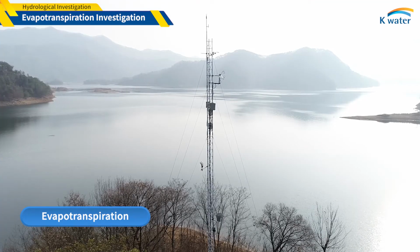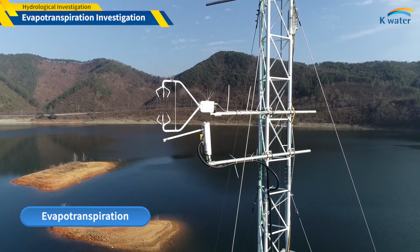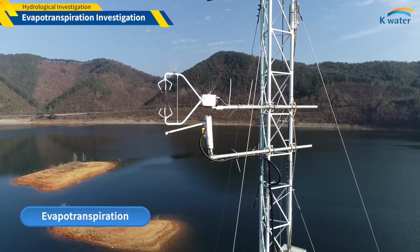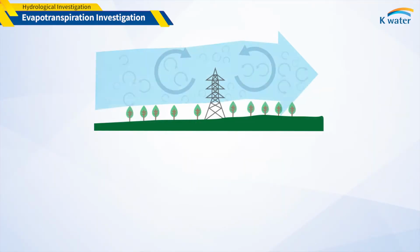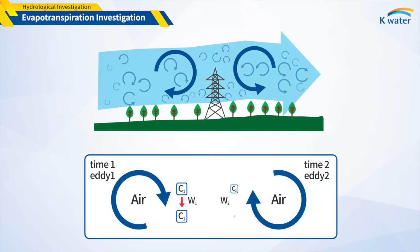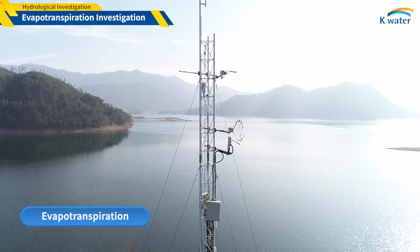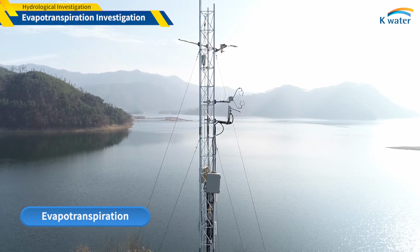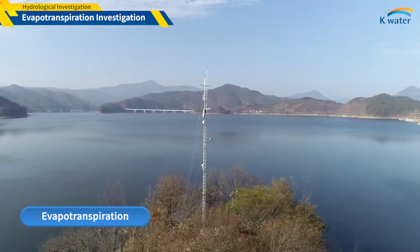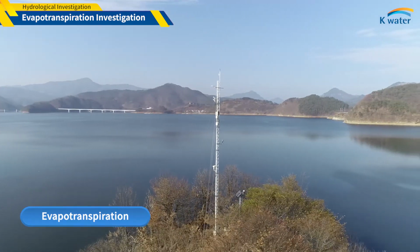First, build an observation tower on a homogeneous and flat area, and install a 3D ultrasonic wind sensor and a gas analyzer for measurement. The eddy covariance method analyzes wind speed and water vapor concentration with a gas analyzer to calculate evapotranspiration at a certain period of time when the wind moves with water vapor. When installing the observation tower, considering the type and height of surrounding vegetation and the weather conditions, it must be carefully installed so that evapotranspiration can be calculated to represent the watershed.